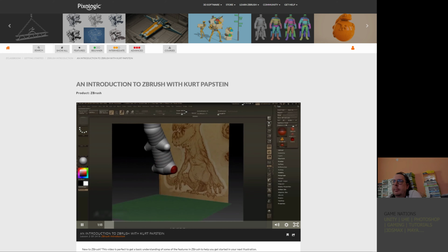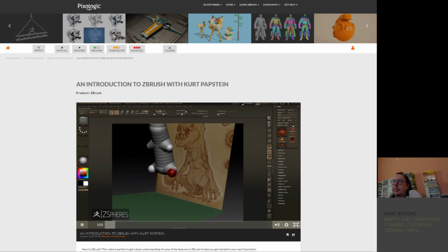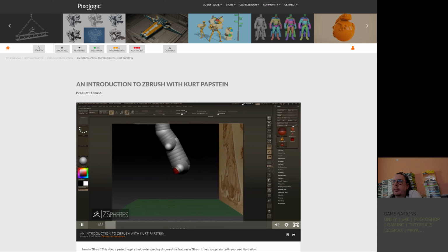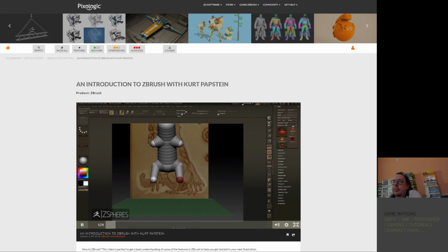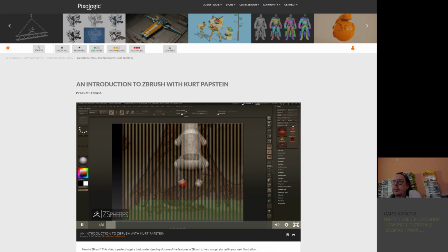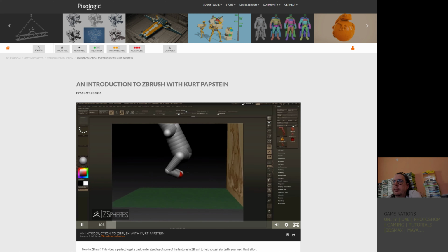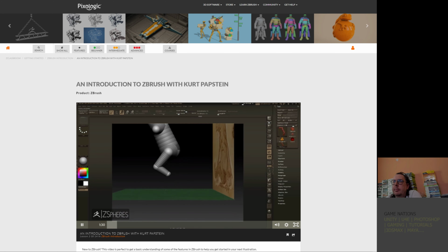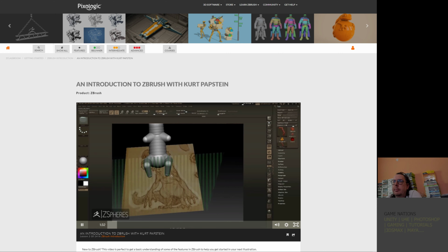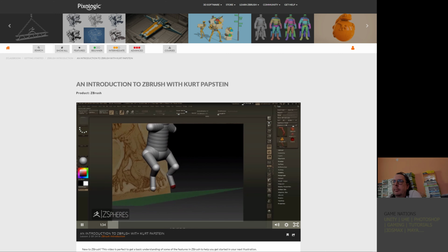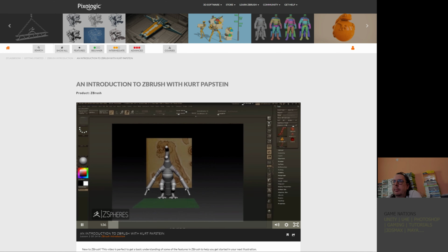There are many ways to begin a sculpt inside of ZBrush. Base mesh creation with Z-spheres allows you to treat the beginning stages in a traditional sculpting fashion, acting as a flexible armature to quickly block in the overall shapes of your design. This gives you, the artist, the freedom to move, rotate, scale, and adjust the core structure.